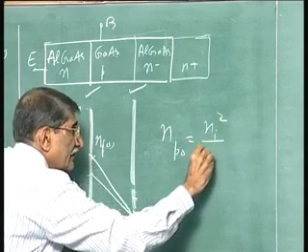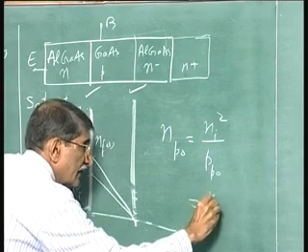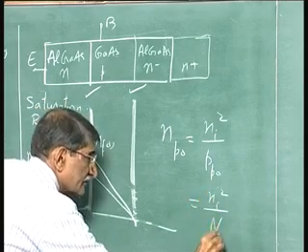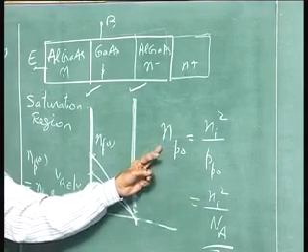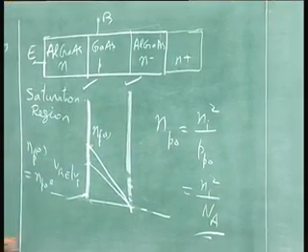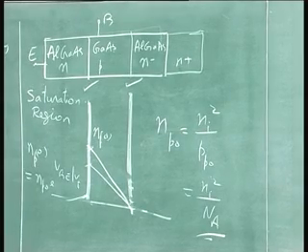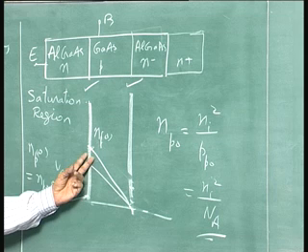Ni square divided by Pp0, which is ni square divided by doping. That increases, and that increases, np0 increases, current increases. This is a simple way of understanding from the formula we have put in that slide there. So, for a given voltage, the current is more.